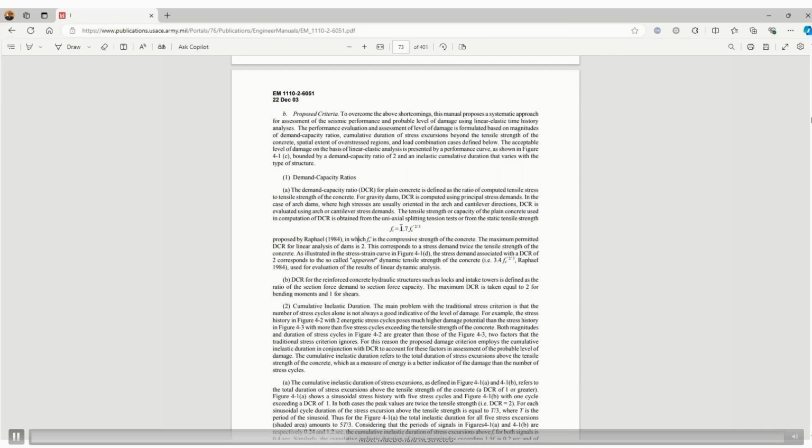If you compute the bending moments in your normal building beams and slabs, and compute the tensile stress there, M by Z, you will find that most of the times those stresses are lesser than this. Sometimes it may be larger also. That would mean in our building columns, slabs and beams we don't require any reinforcement if we consider this tensile strength. This tensile strength is higher, in the range of 2 MPa or something.